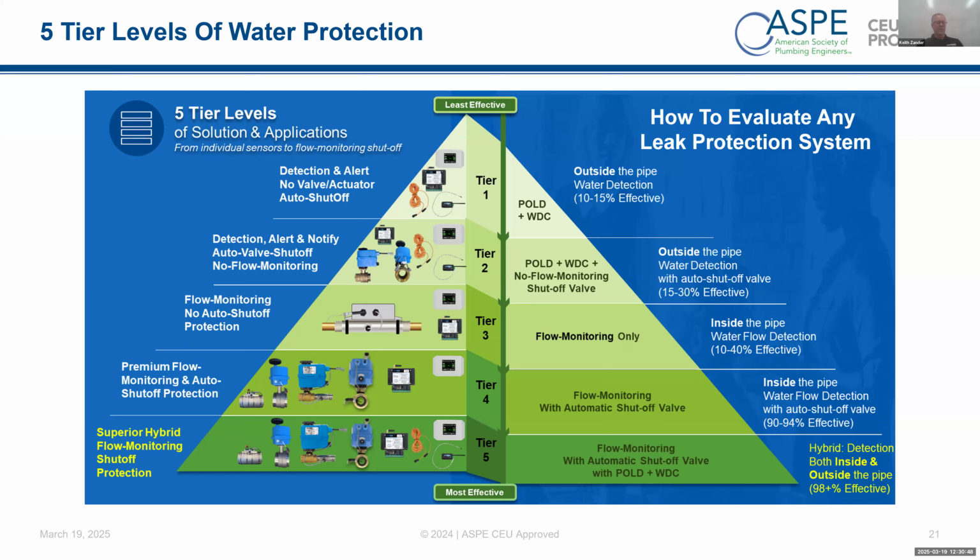So we see a lot of this on HVAC applications where you typically have a secondary pan, and it's normally applied to that. So tier 1, it's going to notify you, it's going to scream. We got relay outputs, so if I get triggers on that, then I can shut at least your modulating valve off or something on the HVAC. That's one way to do it. Or depending on how it's applied, you may just want to put a ball valve or something on there and shut it off if the modulating valve is inside and you don't have those electronic controls in there.